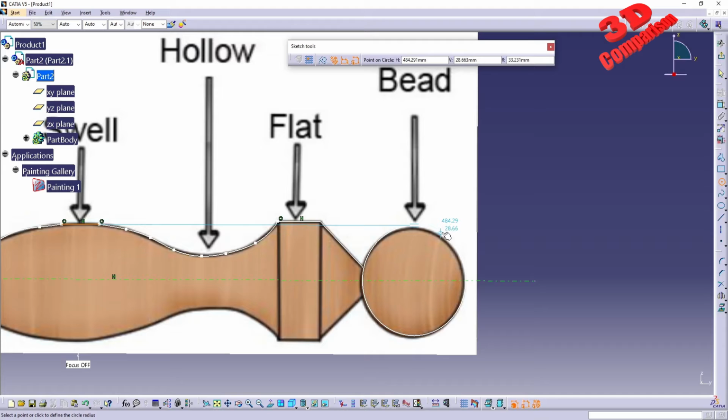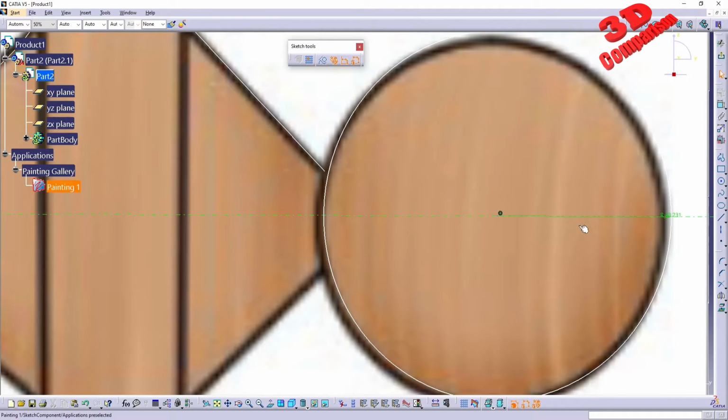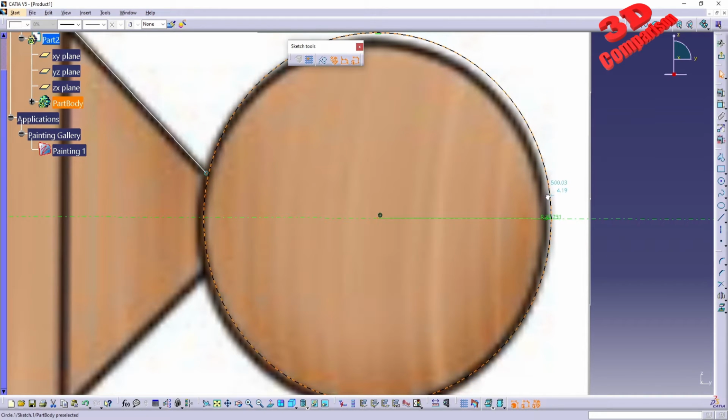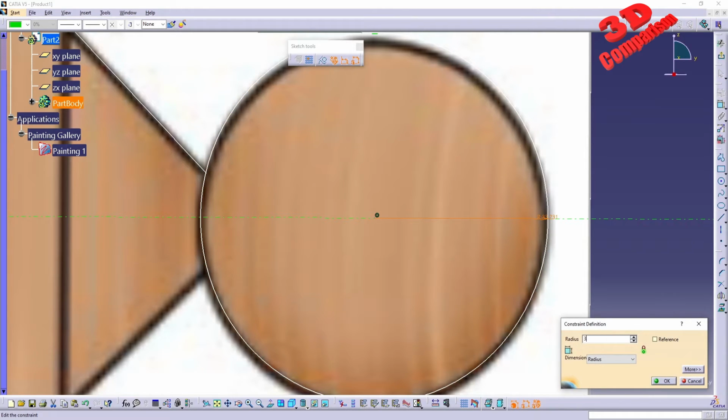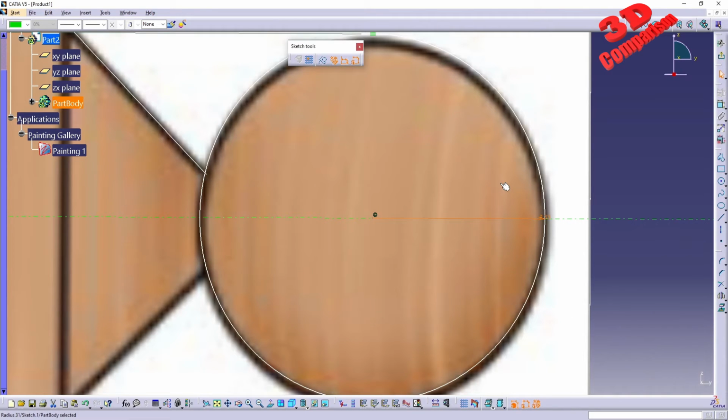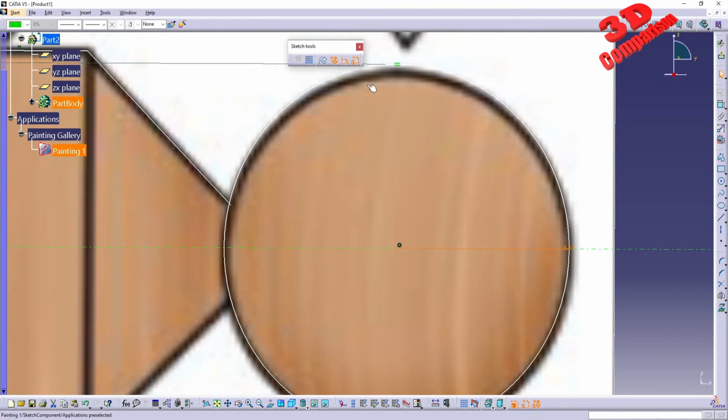And over here I will position a circle. I have the possibility to increase. This will translate the circle, as we can see, but if you want to change the radius, you can double click over here. I'm going to make this 32, for example. And now again, I have the possibility to move it around. But for this case study, I'm going to increase it to 33. And if over here it's quite larger, I can just move it aside.